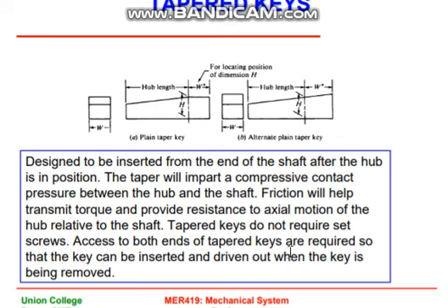Access to both ends of the tapered keys is required. Both ends should have access. Why? Once you insert it, another time you have to drive out or take out the key. You insert the key from one side, and you remove the key from the other side with the help of some rod and hammer.